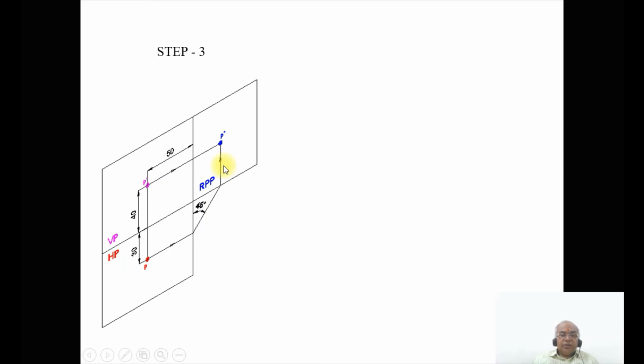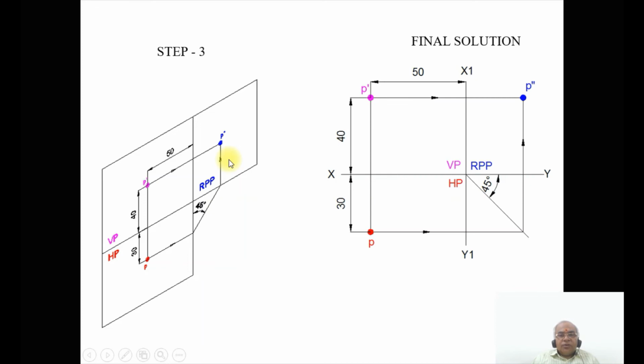So the conversion from the vertical direction to the horizontal direction will take place with equal value only when you are rotating by 45 degrees, because when it is projected here, this vertical distance is going to become 30 mm here, and this also has to be 30 because when it is rotated by 90 degrees, that distance is converted into the horizontal direction. So obviously this should be at 45 because tan 45 degrees is the opposite side by the adjacent side. And where you have the front view on that line, you will get the side view. So this is how you will be able to get the final solution.